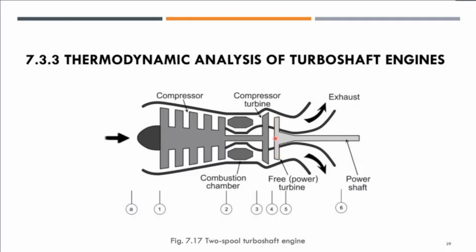The free power turbine is not mechanically connected to the main shaft, which is the compressor and turbine connected into one spool. This is a single spool, and the other one is the two spool, a turboshaft engine driven by a free power turbine.